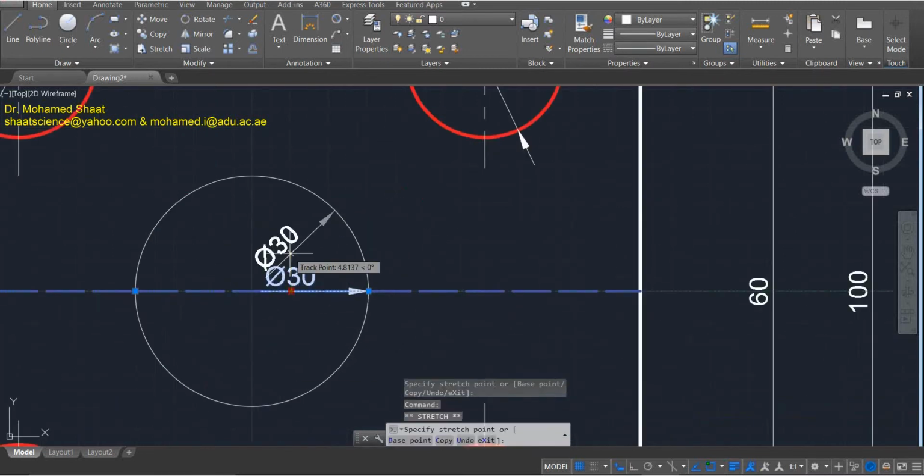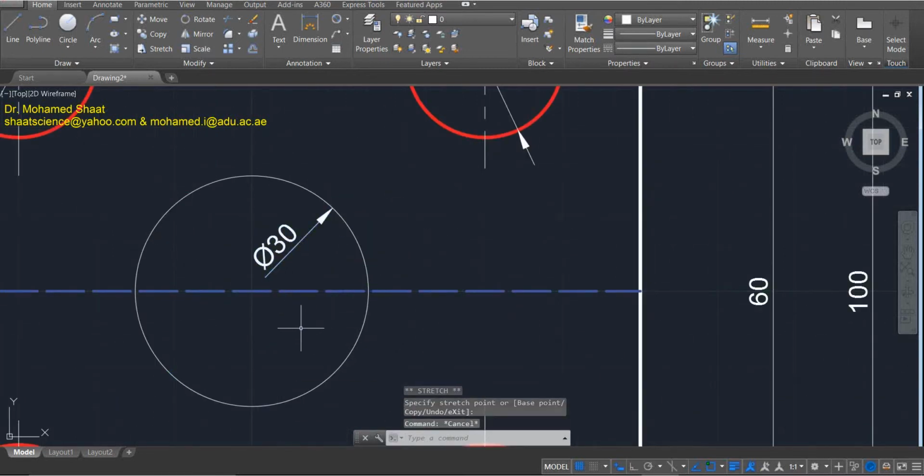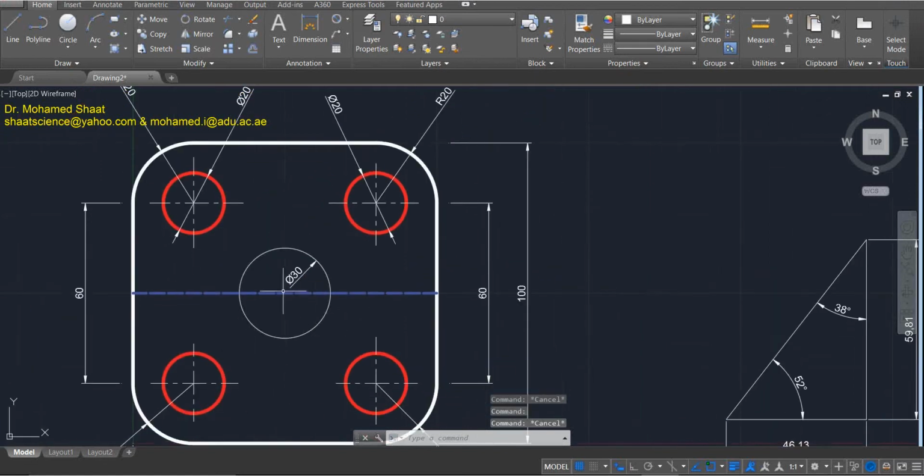So what I'm going to do is squeeze the diameter inside the circle itself, as already given here, and I'm going to use phi to recall the diameter. So as I said, do your best to add the dimension outside the object, but there are some specific dimensions that we have to add inside the object, like the case of a circle in the center here.